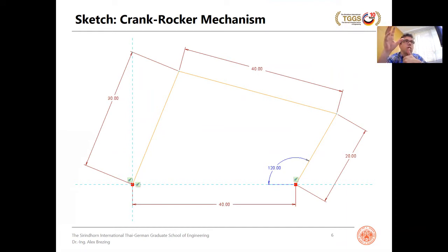You then start a new assembly file. You assemble that skeleton in there as the first component. And then you can basically make rough component models for all the actual parts. Now, I only did one, which is the linkage part of the middle member, and then put that into the assembly and show how you can change that position. That will be your first exercise. I'll give you, let's say, 15 minutes for that, and see you in about 15 minutes.